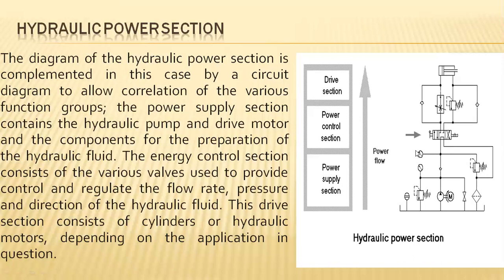The gauge identifies the nominal amount of pressure to be supplied to the system, and it operates at a safe pressure because the pressure relief valve traps the additional pressure attained by the fluid, and that fluid is drained back to the oil reservoir after filtering.